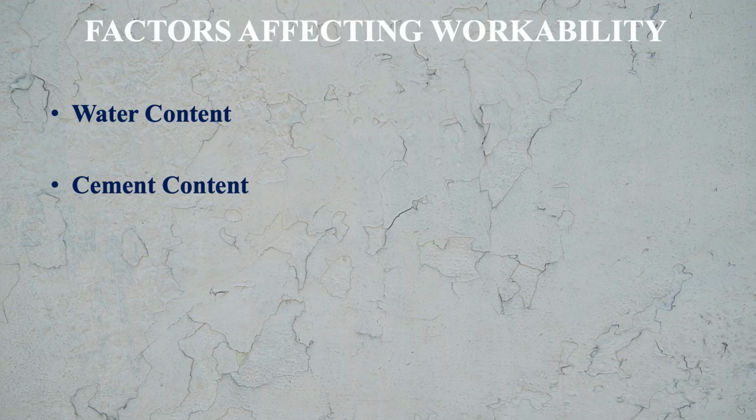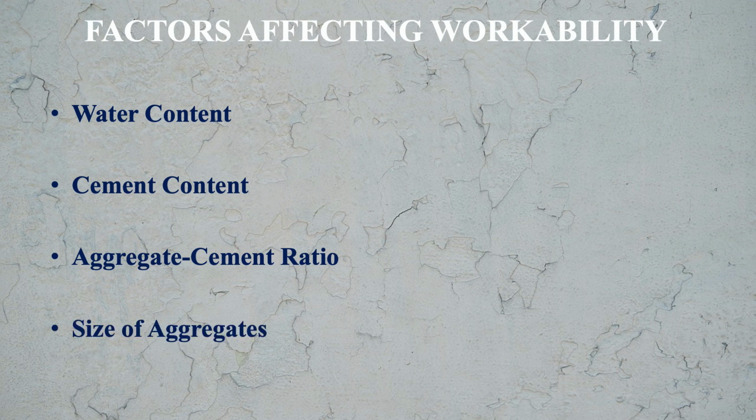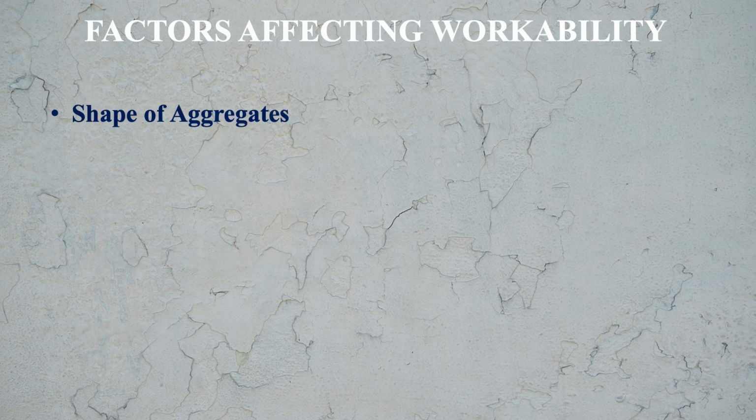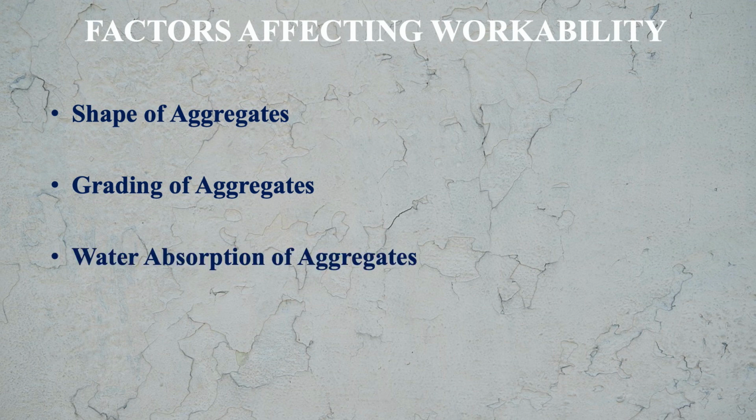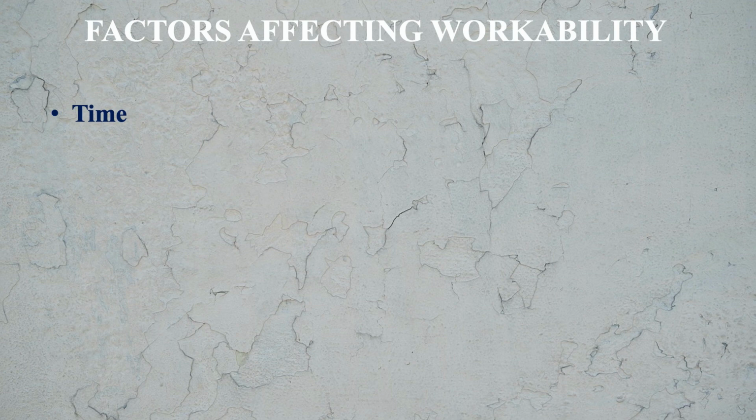These factors are water content, cement content, aggregate cement ratio, size of aggregates, shape of aggregates, grading of aggregates, water absorption of aggregates, temperature, time and admixtures. These are the factors which may affect the workability. Let us discuss these one by one. First, we start with water content.